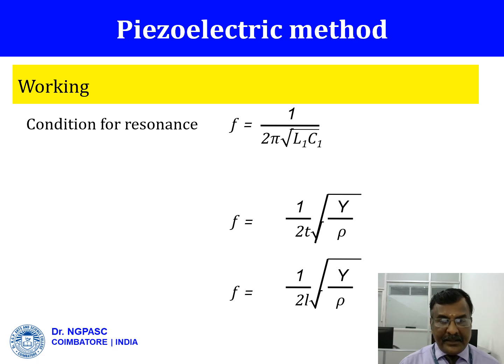When the alternating EMF is fed to the crystal, it will oscillate. The crystal will oscillate with the maximum frequency when the frequency of the tank circuit is equal to the natural frequency of the crystal. When the piezoelectric crystal is placed along its thickness in between the plates,